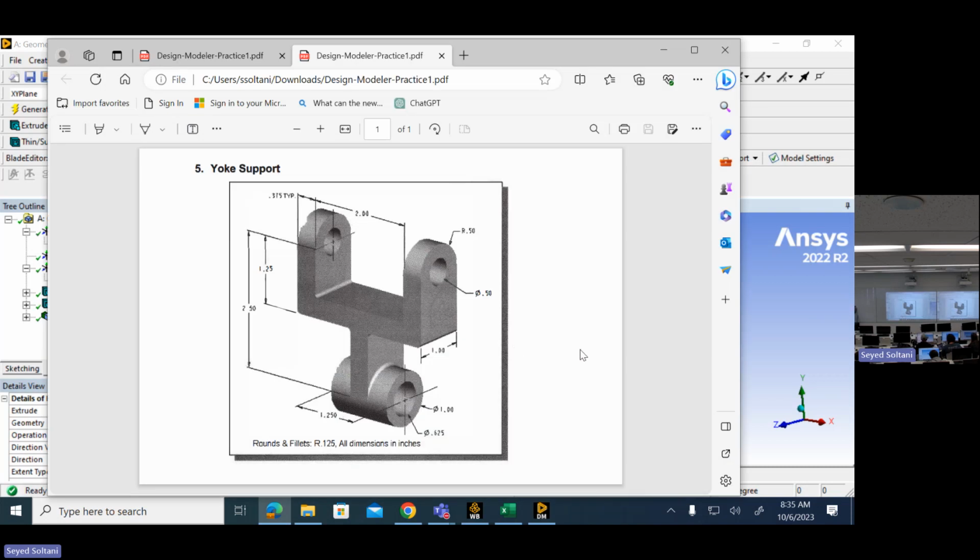All right, so this is how I would do this, all right? I'm going to first add this shape, see? The rectangle, take away from it the circle. And then do the extrusion by this much, 0.375 or half of it, when I do that both symmetric.